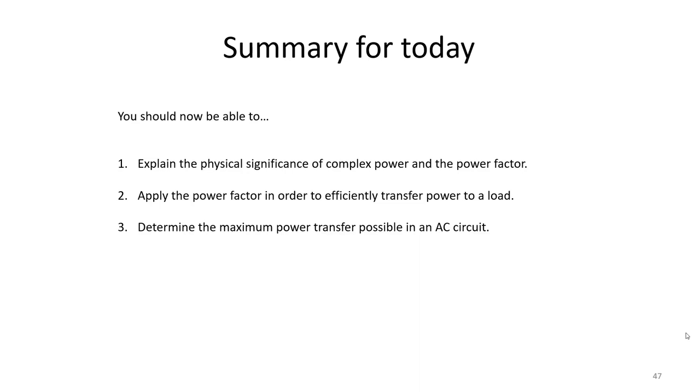All right, so let's go ahead and wrap up here for today. You should now have a greater understanding of the physical significance of complex power and the power factor. Please make sure you've added all those equations to your toolbox so that you have them handy for our homework. Also, make sure you understand how the power factor can be used in order to efficiently transfer power to a load. Remember, most of the time we want our power factor to be as close as possible to 1 in order to maximize the real power that we're able to get.